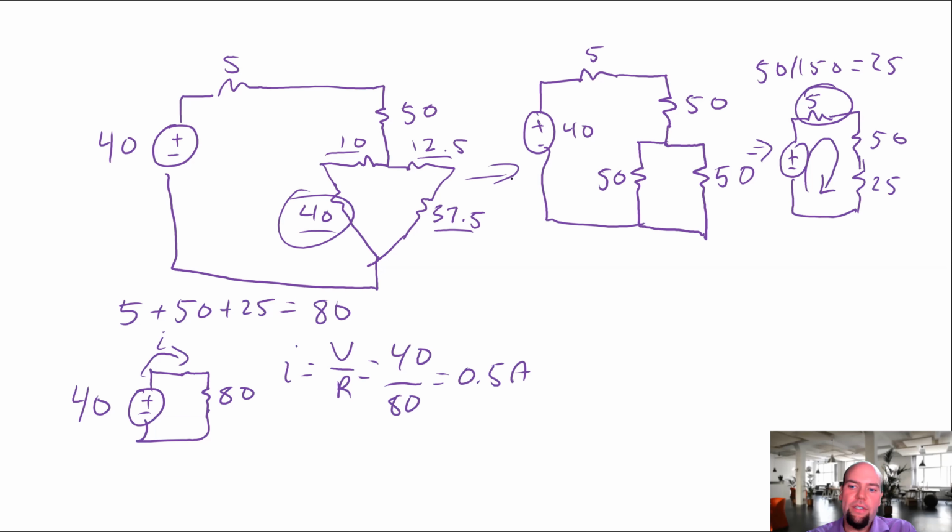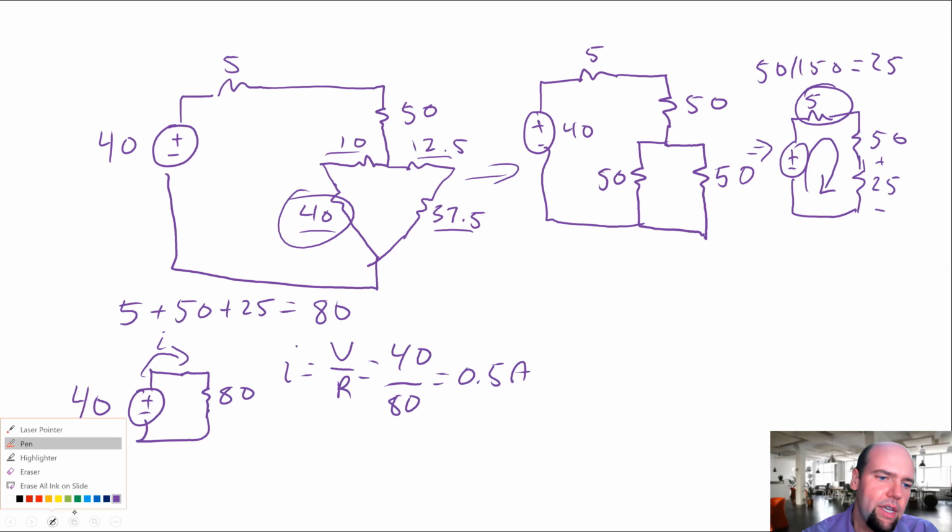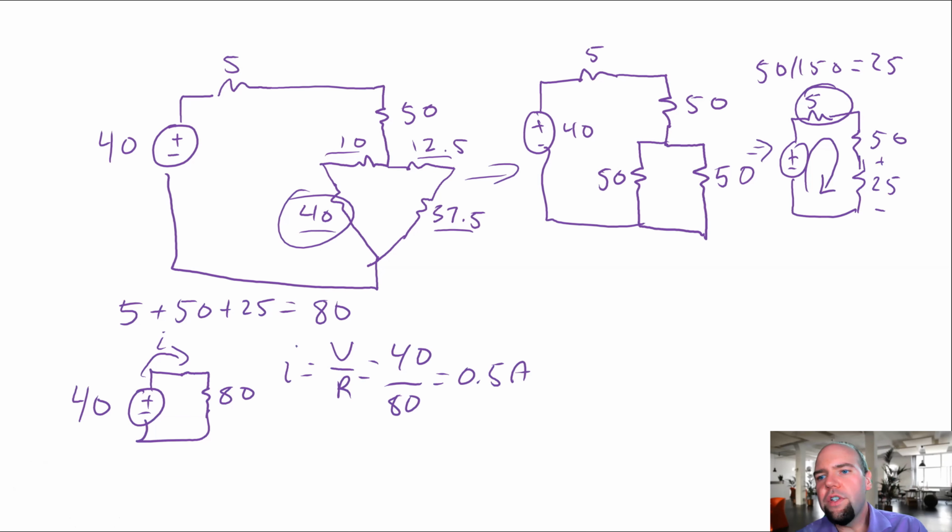There's several ways that we could do this. So for instance, we could use voltage divider to find the voltage across this 25. I'm starting to get messy here, so I'm gonna change to red. We could apply that to this circuit drawn here. And then we know that 25 is here. So whatever this voltage was, that would be the voltage between here and here. And then we could do a voltage divider on this little section of our circuit, right? We know there's this many volts across these two resistors in series. So we could do a voltage divider to find the voltage across the 40.